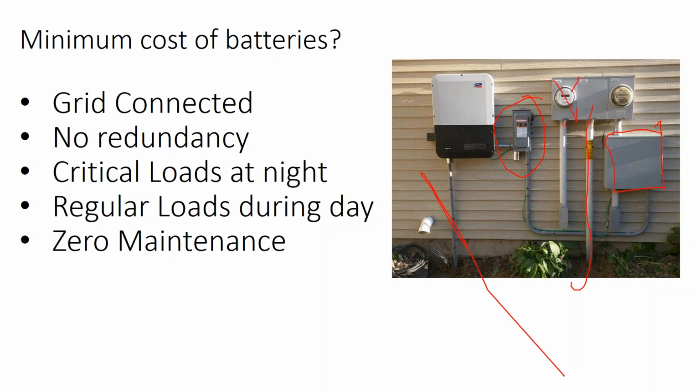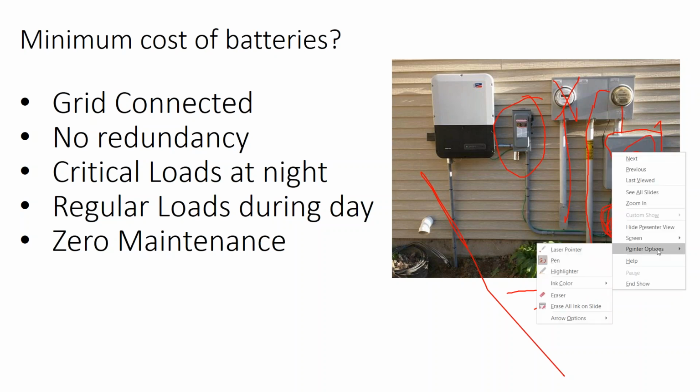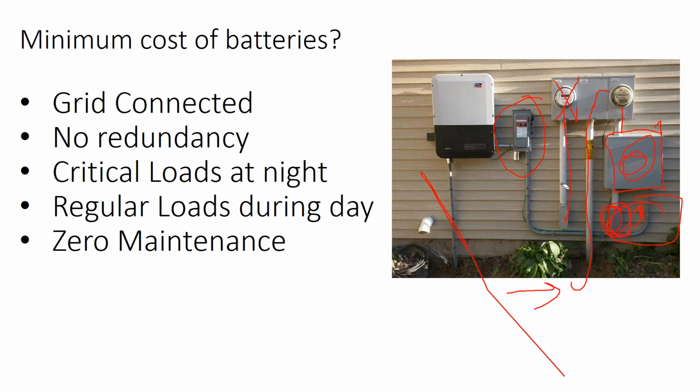Ignore this, this is a separate service for a heat pump. That's a standalone utility program. But we've got our underground lines coming up from the utility, going through our meter. And then at this point, this is the pass-through box that's going into the wall. On the other side of this wall, you'll find a basement with an electric service panel. So all this is right here is a junction box for our supply side connection.